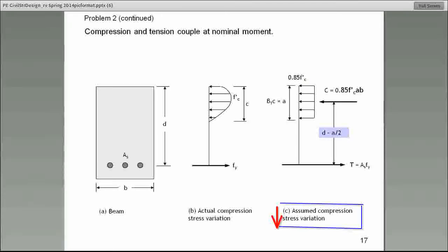So here we have the stresses. 0.85 F prime C are the stresses. But I need everybody's help here. Guys, if I give you the stress and I ask you to please find the maximum force associated with it, what would you do? Critical thinking. What would you do?